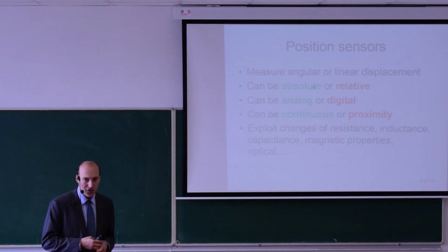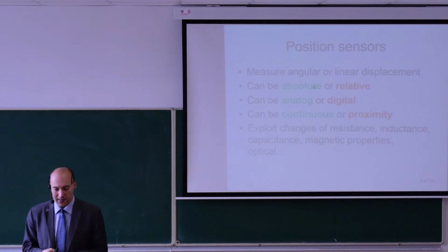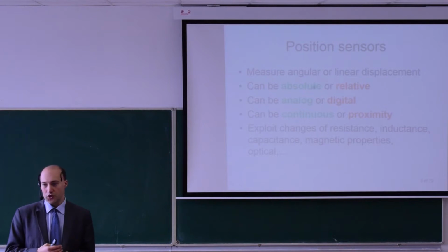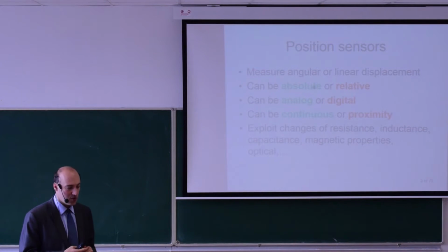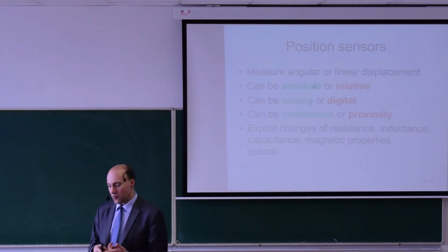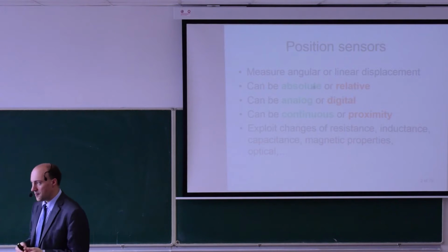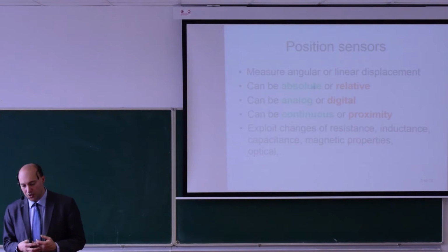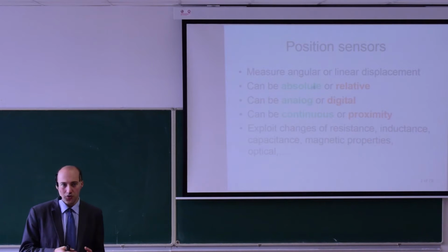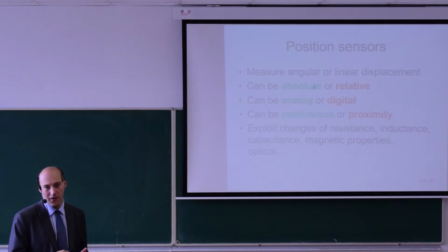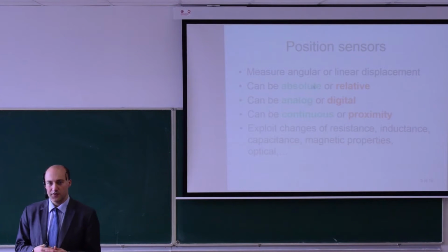The advantage of relative sensors typically is that they have a finer resolution, let's say roughly 10 times larger resolution than absolute sensors. So if your application requires the absolute position, then you will have lower resolution. But for applications like electric machine control, that's not an issue. But if you need a really fine resolution, you will definitely need to go for a relative sensor.